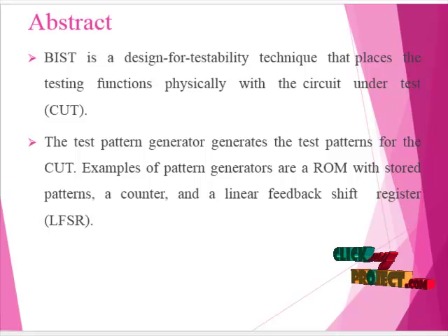It is comprised of a linear finite state machine, a linear feedback shift register or a ring generator as the finite state machine, driving an appropriate phase shifter, and it comes with a number of features allowing this device to produce binary sequences with pre-selected toggling activity.